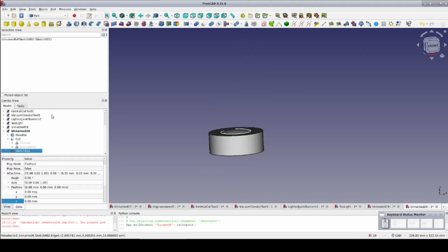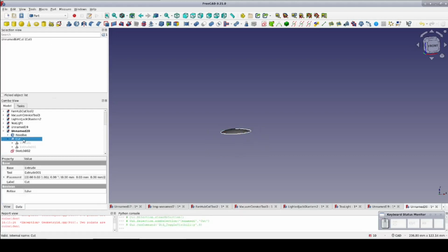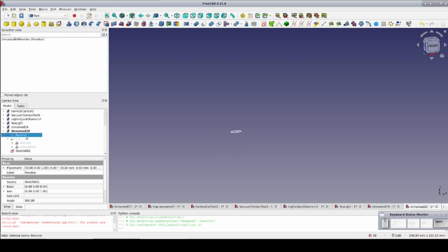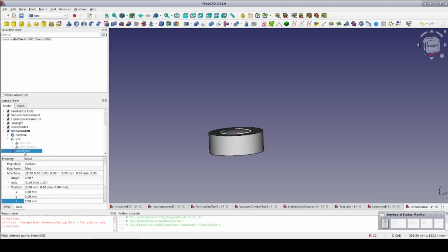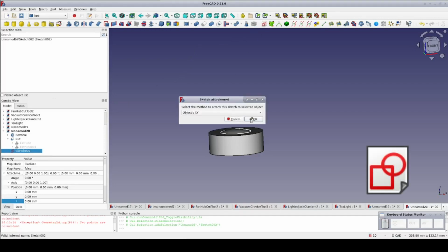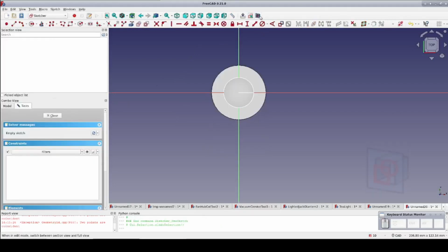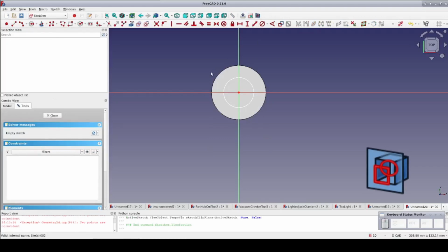Close the sketch. Since the first sketch is on the flat face of the top, I know I'm going to need to offset the entire flame by some amount to get it into the correct position. Right now, the base of the flame is inside the dome. To make moving things easier later, I'm going to create the second sketch attached to the first sketch. That way, moving the base of the flame can move the entire flame at once.